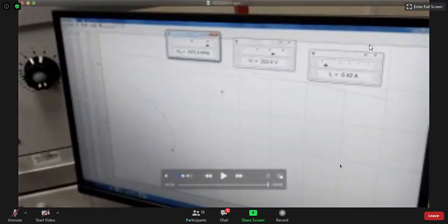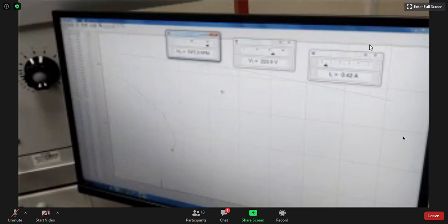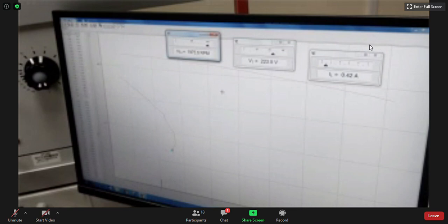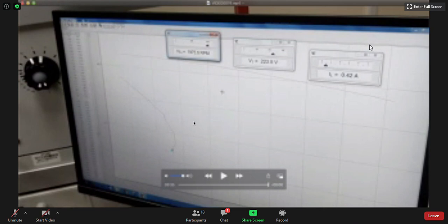Okay, gentlemen, that basically ends our experiment. You can see that this red color is the cumulative compound and this black color is the shunt generator. So in your lab, if you open your lab manual, we have three graphs. The first graph is IF versus EA, which is a straight line. The second graph is your part C, the shunt generator, which is this characteristic. Basically, this is a very sharp characteristic as compared to cumulative. This red color is the cumulative compound, a lower characteristic of the DC generator.